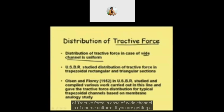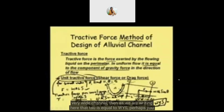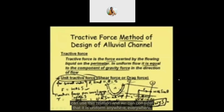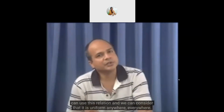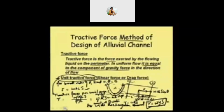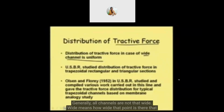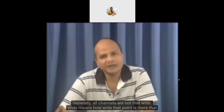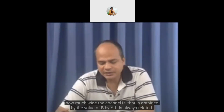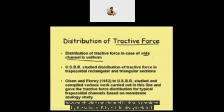So distribution of tractive force in case of wide channel is of course uniform. If we are getting a very wide channel, then as we are writing here that tau is equal to Ws, perhaps we can use this relation and we can consider that it is uniform anywhere, everywhere. But generally all channels are not that wide, and again wide means how wide, that point is there. How much wide the channel is, that is obtained by the value of B by Y.